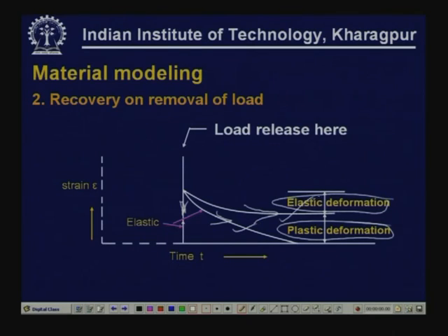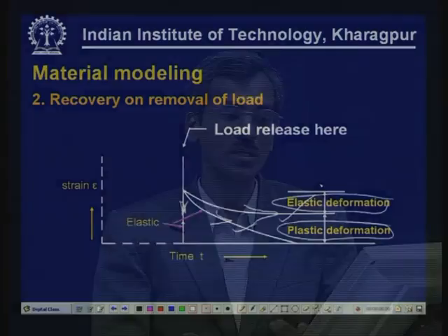This can be considered to be elastoplastic, partly plastic. So, depending upon the material that are used, different material will have different behavior, but hardly any of the pavement material can be considered to be having instantaneous recovery. Most of this material recovered to a great extent depending on the condition to which these are subjected to, but most of the recovery is over some time period.